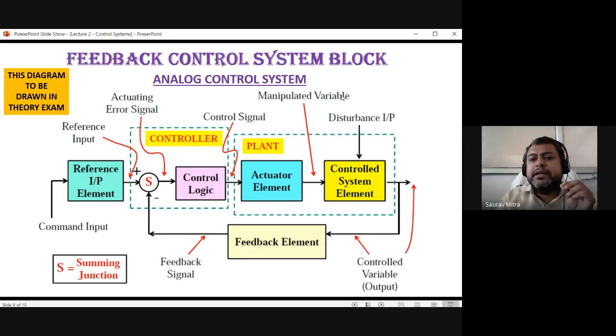Suddenly somebody comes from outside and puts some very cold water inside the process. That's an external disturbance. That is uncalled for. You did not expect it. As soon as a huge amount of energy, and cold water is also a type of energy, is added, that's a disturbance. As soon as the disturbance is given to the system, the temperature will fall in one shot, to 50 degrees centigrade. So this is the downside of a closed loop system: the disturbance affects the output, and the output deviates from the actual command input or set point.